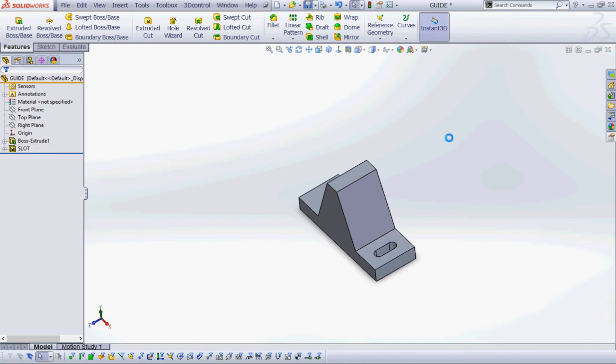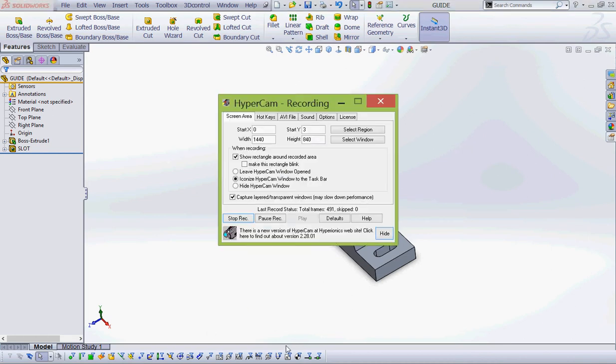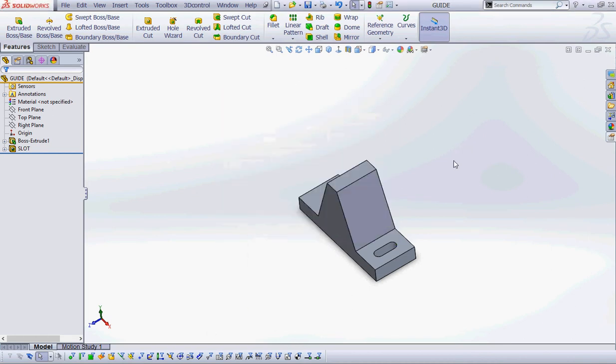And I had add dimensions enabled, and that automatically adds the dimensions for me. Isn't that nice? Then all I have to do is click on the dimensions to change them. So I right-click select, and then I double-click on the dimensions. In the book she has it as R3, but the dimension that's given is the diameter dimension.